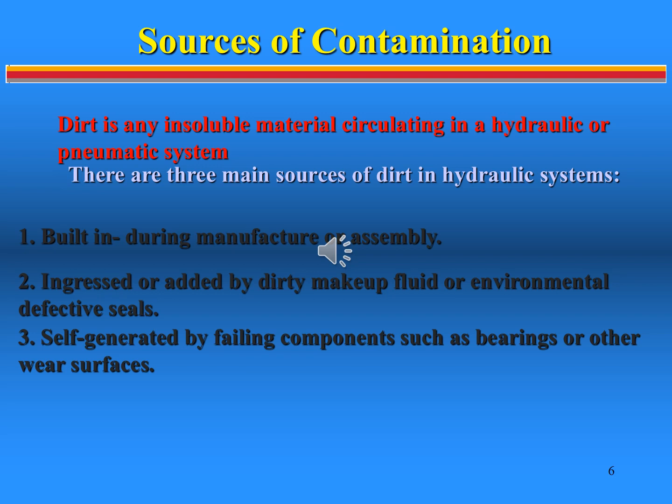In some cases, the wiper seals on a cylinder may be defective and dirt may enter the system because the seals are no longer wiping the rod clean. Another contaminant source, component wear, is normal but creates very hard particles which may accumulate and produce abrasive compounds, accelerating wear on sensitive machine surfaces.